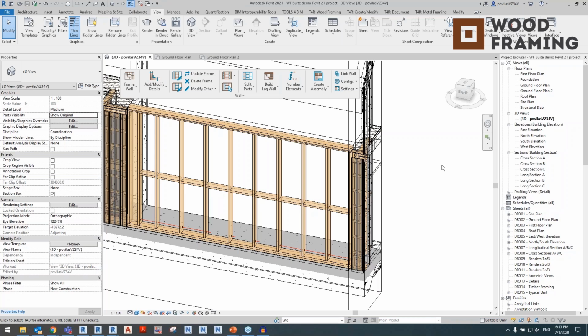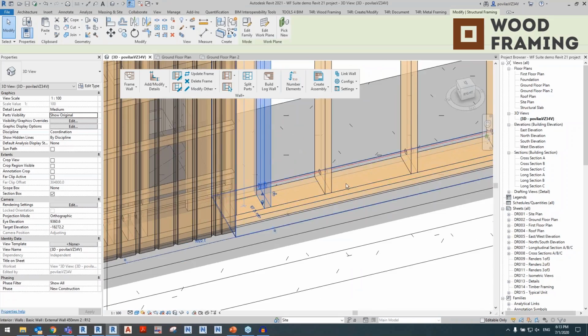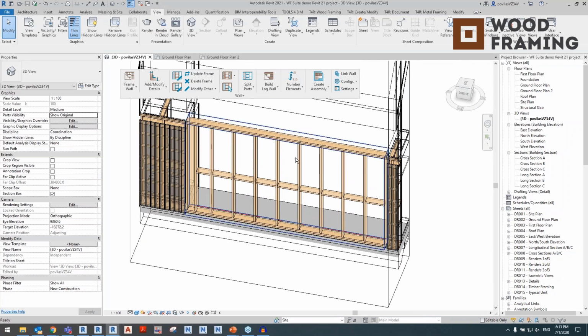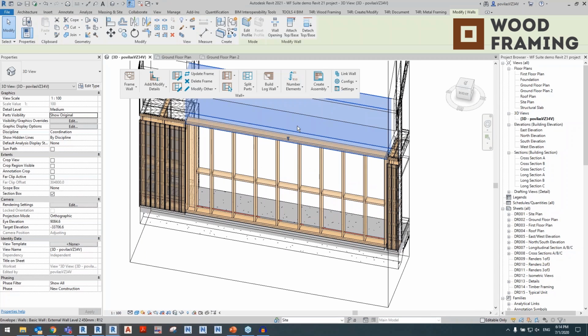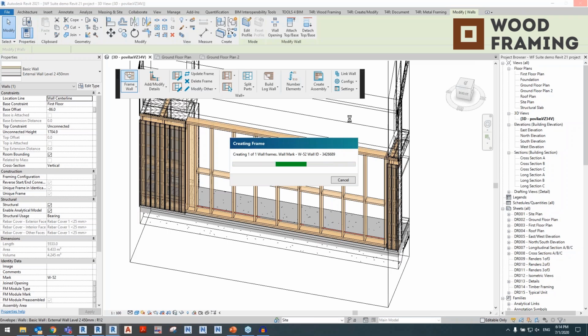on our YouTube channel. Okay, so that additional stud I've placed is in place. Now I'm going to frame this wall above, and once that's done, I'm going to align my studs. So ground floor wall with first floor wall, I'm going to align those studs.